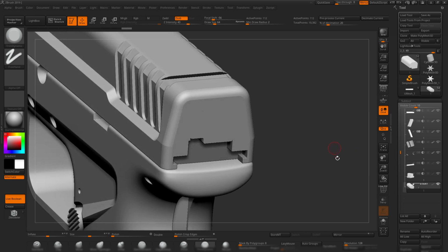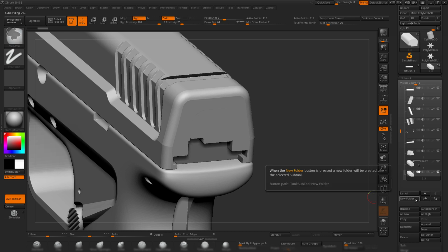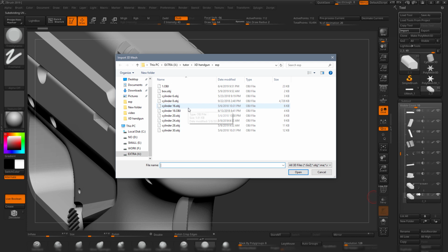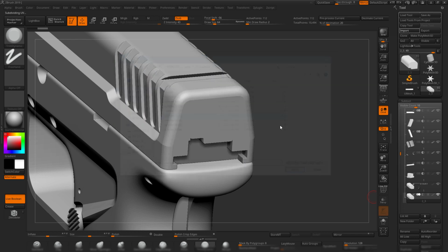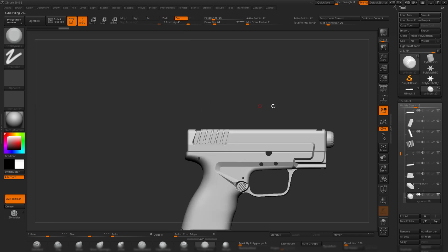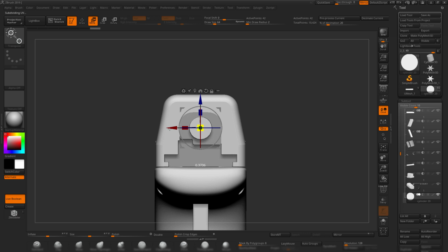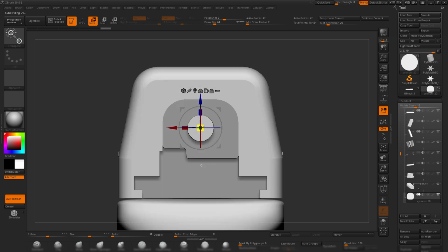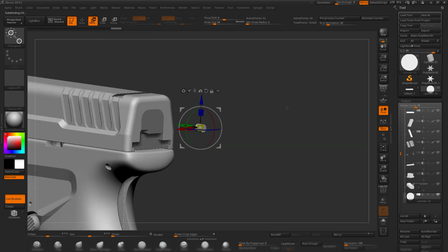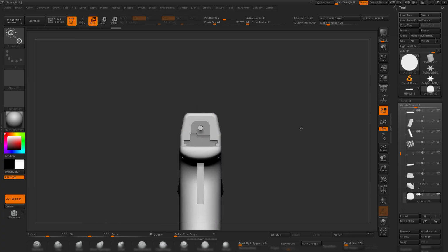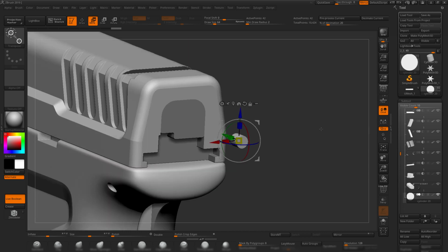So let's make this cocking indicator. Duplicate this guy and let's insert there a cylinder, which is, I'm going to use 20. It's already in the center of coordinates. This is good. Shift D and, well, right now I'm not sure if I'm going to bake this object or model, so just in case I'm going to model this, which is kind of unlikely.